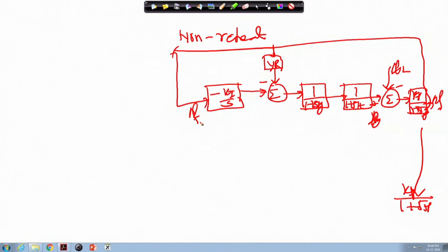In this case, regarding optimization, we have not talked about it yet. For the isolated system we talked something about optimization. So this is my delta P G, and this is your delta P V, and this variable is delta X C, this is the non-reheat turbine, and this is output U. But we will now consider the output U as a state variable, because our objective is to find the optimal value of K I. How will we do it?